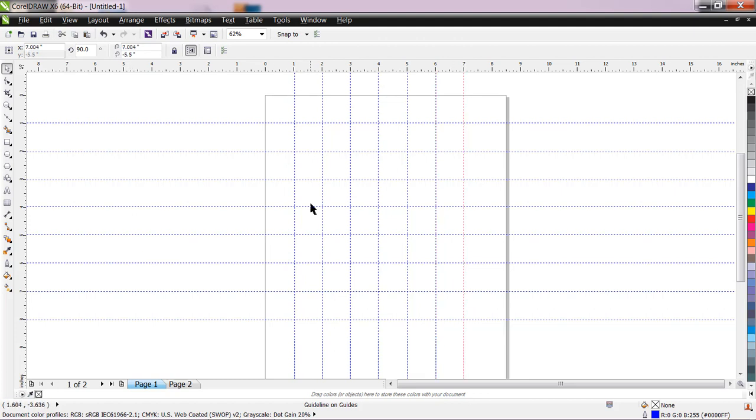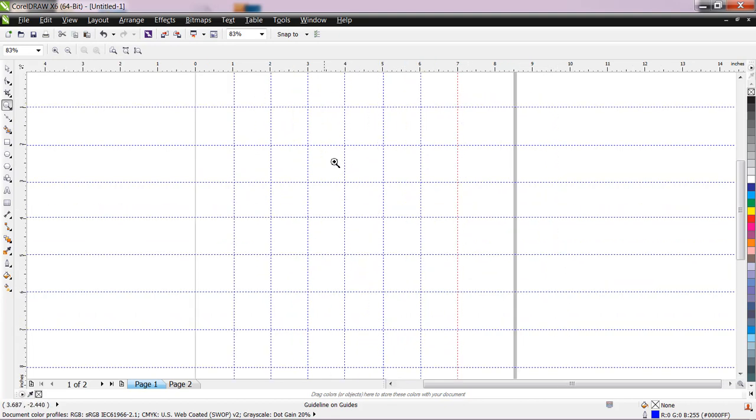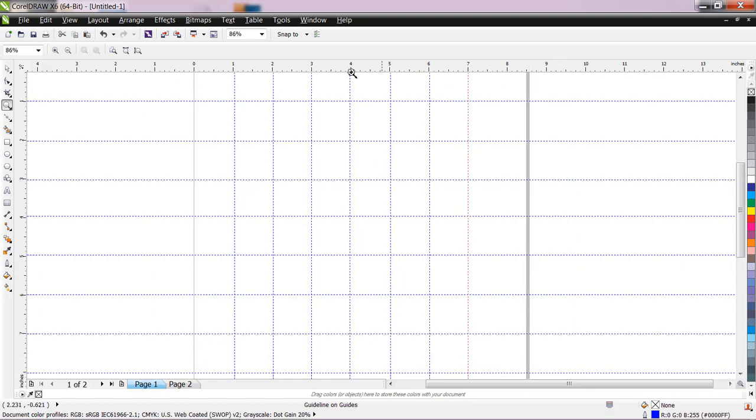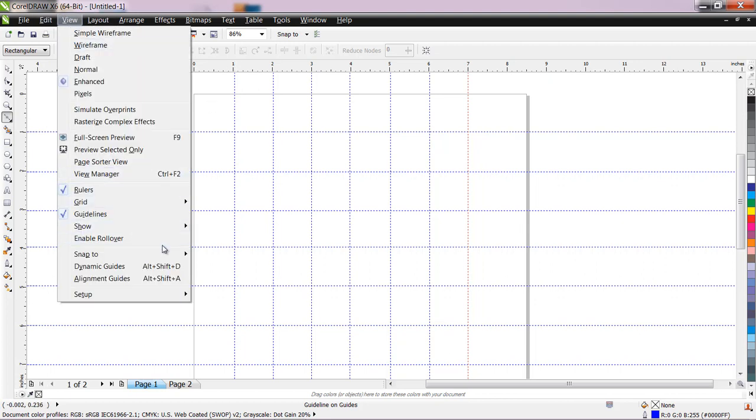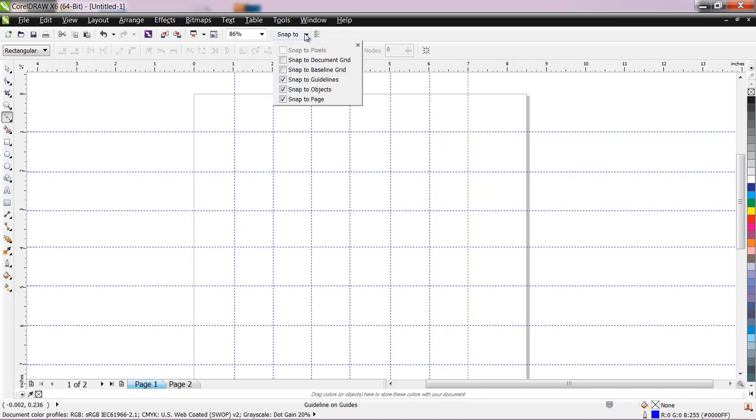Okay, now our working area is only this one. Therefore, click on zoom and let us zoom this area. This is our working area. Okay, now let us create a curve. For that purpose, here we use Bezier tool. Click on Bezier and don't forget to set snap to guideline. Here also you have the setting of snapping. Always keep snap to guideline while using guidelines.